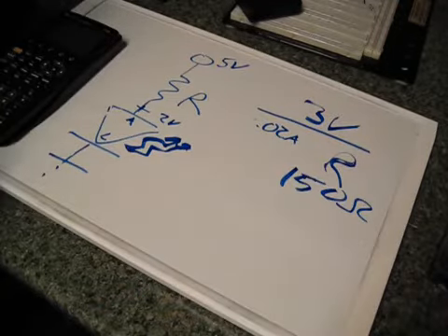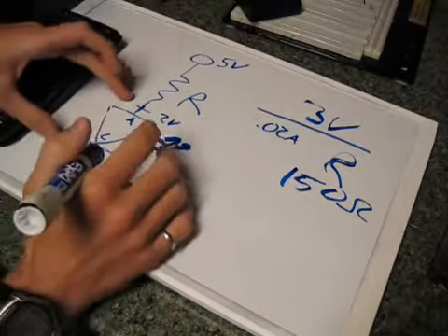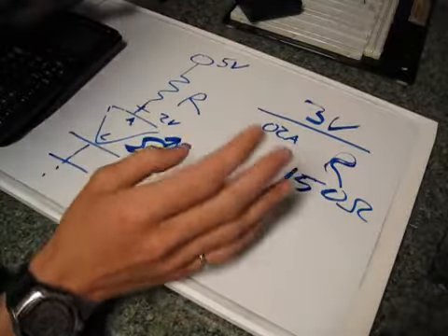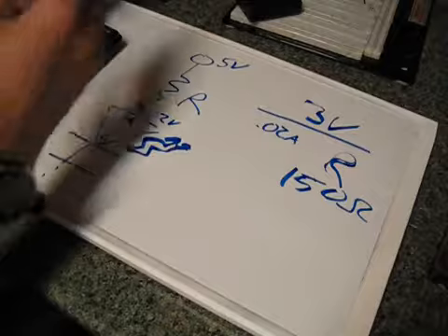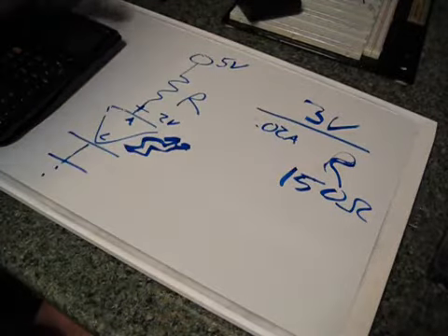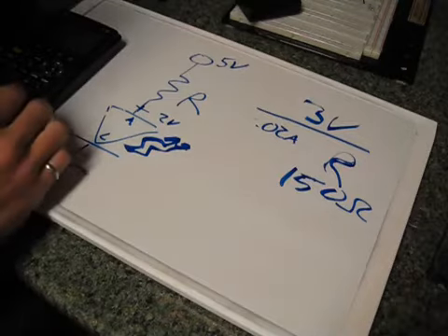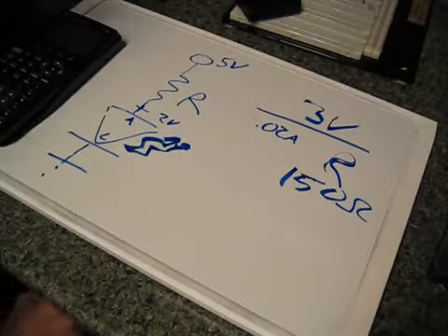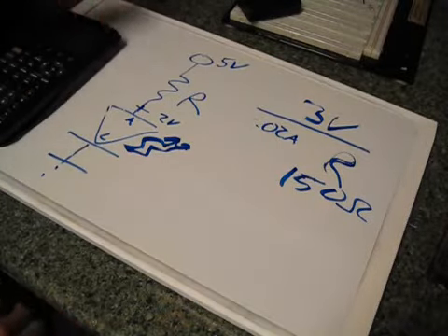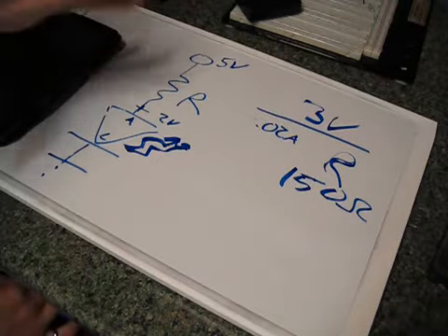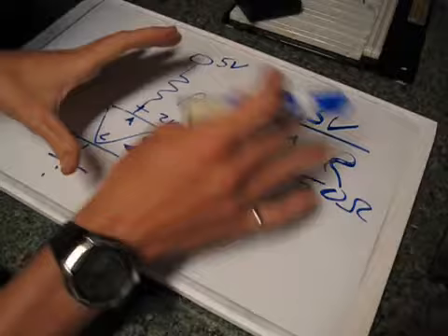150 ohms. So if we use a resistance of 150 ohms, we would be giving this LED its maximum power, which isn't really a good idea. You'd probably want to go at least 10% higher than that, or the next resistor size in your bin, so that you don't burn it out, because you don't want to operate it at its maximum conditions. So maybe a 200 ohm resistor for this application would work. You always see 330 ohm resistors in a lot of these types of circuits.